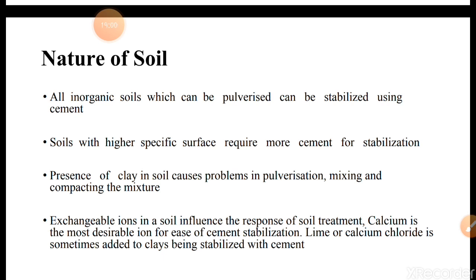Exchangeable ions in a soil influence the response of soil treatment. Calcium is the most desirable ion for the use of cement stabilization. Lime or calcium chloride is sometimes added for clays being stabilized in water.